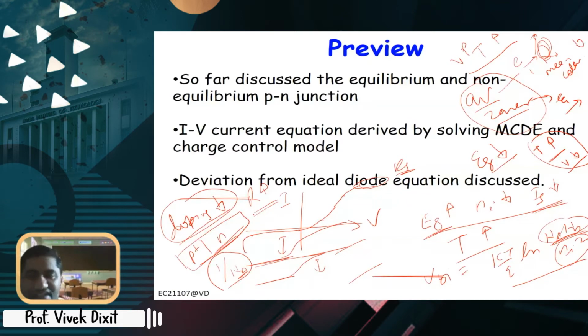It is rather a technique that is used in certain cases. For example, in some photo detectors, if a small number of photons are coming, we have this avalanche multiplication that multiplies these carriers, because a small number of photons will generate a small number of carriers, and they are multiplied by avalanche and then counted. So avalanche multiplication is used for this kind of purpose.